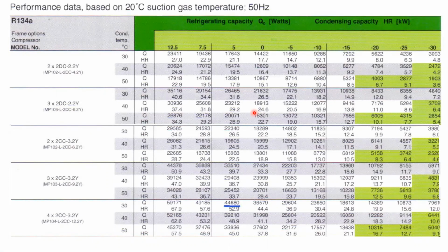Now, this is a typical compressor catalog available from Google or any compressor manufacturers having such kind of catalogs. So these are different model numbers and their performance parameters for various operating parameters. As far as the compressor is concerned, the operating parameters are evaporating temperature. So these are the evaporating temperatures, 12.5 and it goes up to minus 30 degrees Celsius.